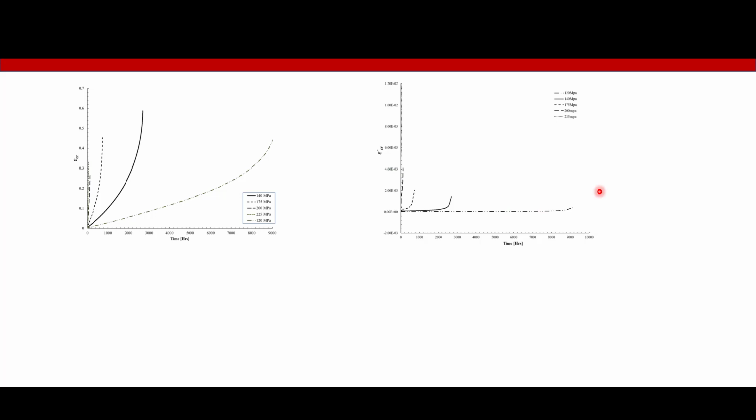And I have found that many students look at this kind of data and say that there is no primary creep and there is only secondary creep, because that's how the strain rate diagram looks. And then the slope increases, so there is tertiary creep. And they will say that this value is constant, so it is following steady state creep and everything is good. But it is not true. If you look at this diagram, you will see that the steady state creep rate is 0.